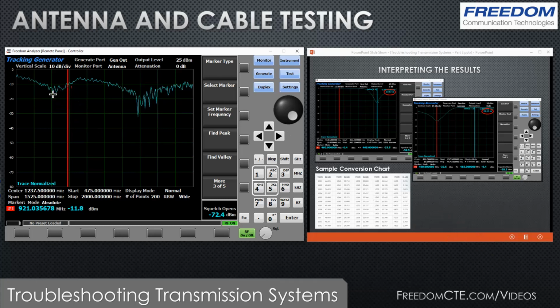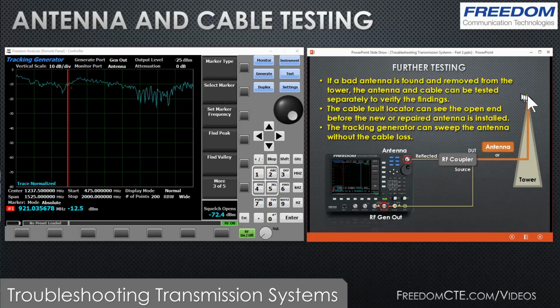Okay, so now we have, from the ground still, determined that this, of course, is not a very good antenna for a base station, but it is performing as it should. Had we determined that we were not radiating enough power, or not as much as we should be, then the next step, we send a tower crew up to the top, and they can bring that antenna down, and we can hook up the antenna directly to the instrument. And now we no longer have to account for the cable loss.